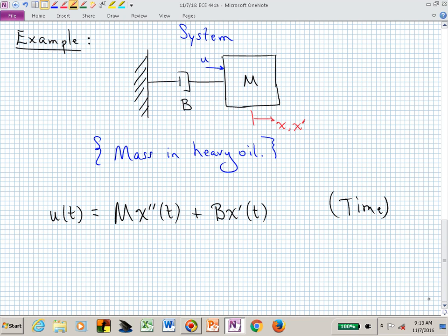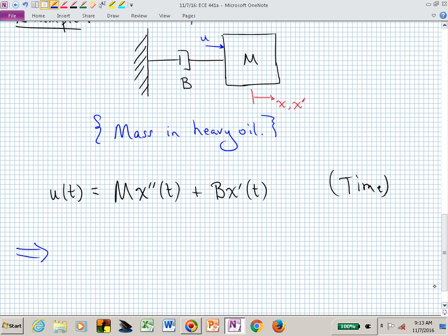That's our time domain equation for the dynamic behavior of that system. And we can take that into the frequency domain, which is where we like to work, because now we're playing in the S-plane. That's where we're going to be sketching the root locus and putting down maybe some additional poles and zeros. What happens when I Laplace transform this equation and I'm really looking for a transfer function?